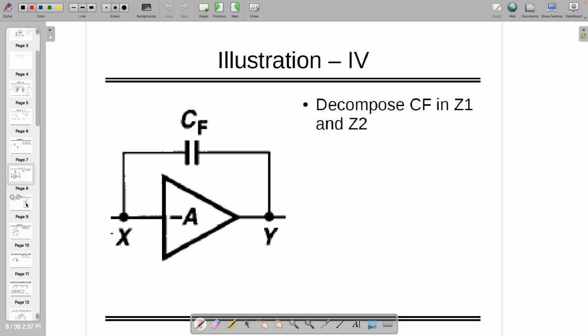Let's go this way. Let's decompose this. You can decompose or not? Even if it's minus, minus is also considered as gain. Okay, so tell me, if there is one capacitor over here, I am keeping these as dotted lines just to show that these are the parasitics. Actually the capacitor is between Vx and Vy only. This is for our understanding, and this is using Miller theorem. So what are these capacitances? What is C1?